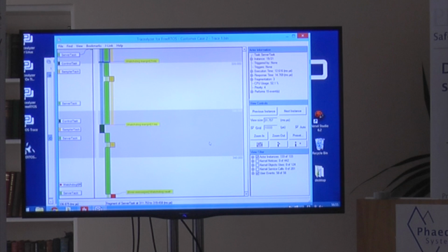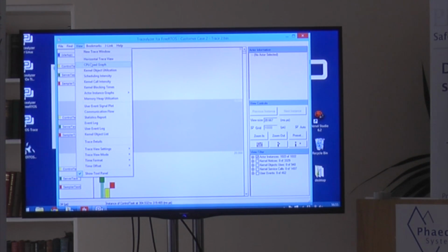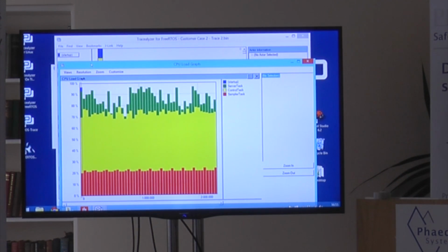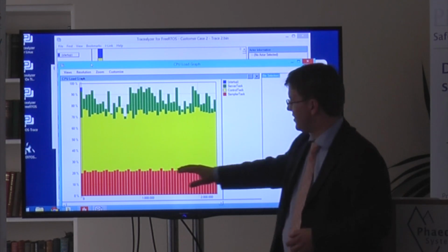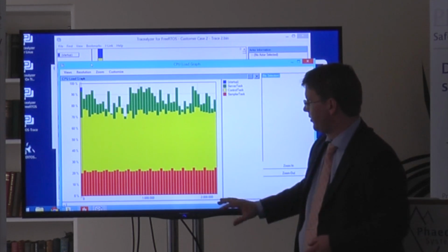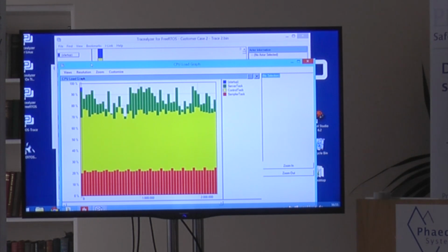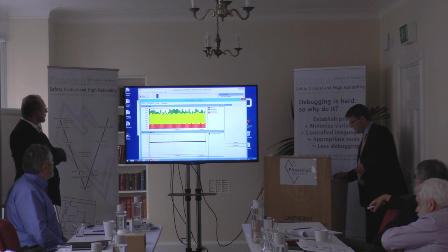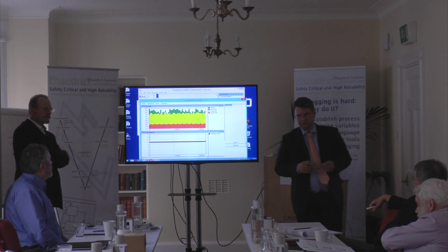So what can we do to change this? Well, they realized that we could actually change the priorities of these two tasks. And when they do this, we get a result like this. Looking at the CPU load graph now, we have a much more stable shape, where this high priority task is getting 20% all the time. And now control task is the middle priority task and also gets a fairly even amount of CPU time. And we don't get these resets. If we plot this margin on the watchdog, we see it's a line now, no anomalies.